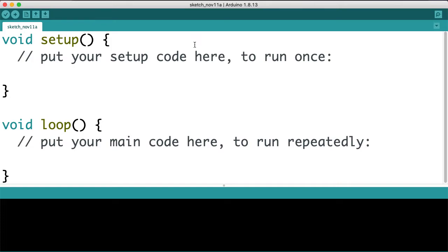So when you're interfacing an LCD to the controller, you need to select your register to which you're writing your data to or reading from, and then you need also to enable so that you're able to write or read from the LCD, and also you need to actually select the data pins that you're using.